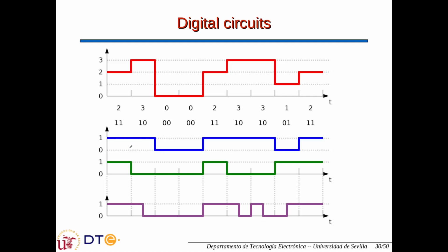we can take this binary representation and make a new single digital signal that takes two different values in any period. So it's a signal that carries 2 bits in every period, doubling the rate, or reducing to half the interval. Okay, so number 3 in this interval could be represented by 1 and 1, and it can be represented by half the time the signal is 1, half the time the signal is 0.